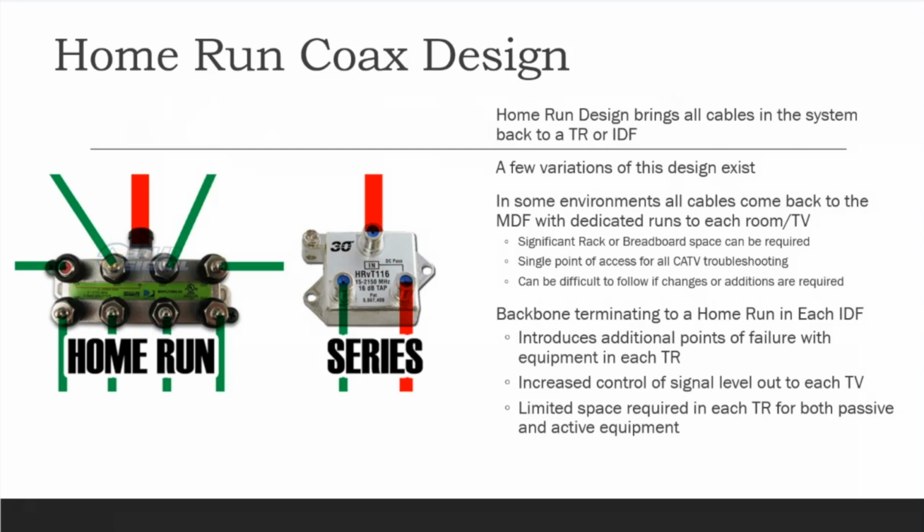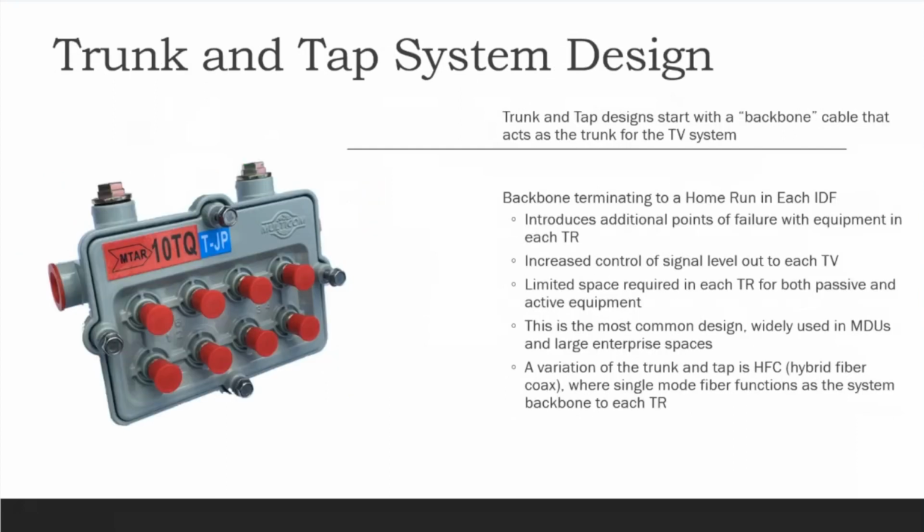It's all being done in that main TR, and then that's it. No amps, no taps, no splitters, no balancing, nothing in line. You just home run. The next one is trunk and tap. Trunk and tap is going to be a little bit different.